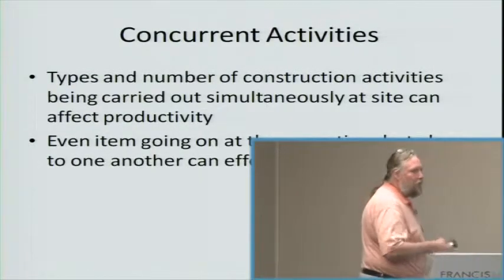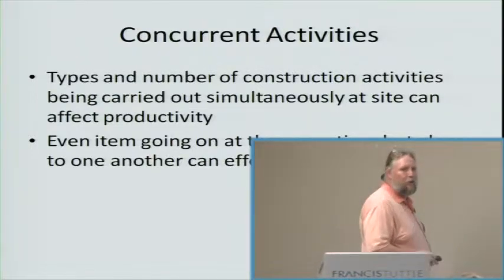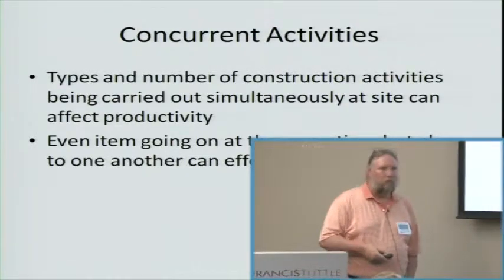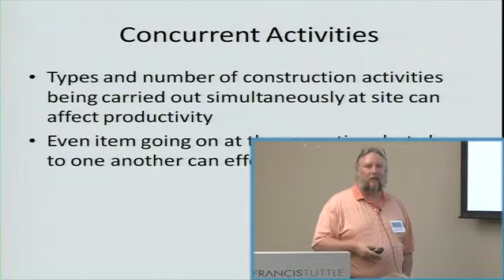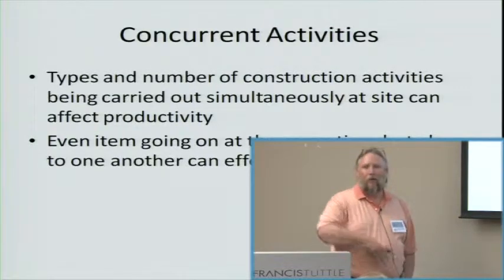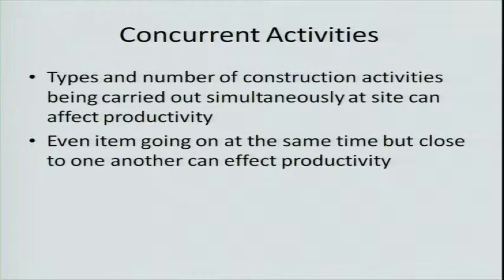We talked about concurrent activities, something on top of you, something below you. Or I need to dig a utility trench while I also need to dig a stormwater trench. Well, I've only got one piece of equipment. It can only dig one or the other. But they're scheduled to go at the same day, at the same time. Well, those are concurrent activities that won't work. You're going to have to adjust your schedule.